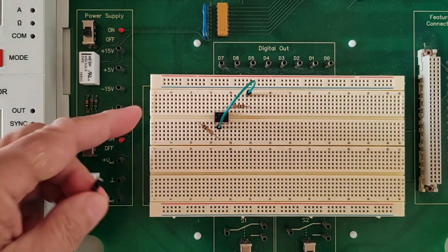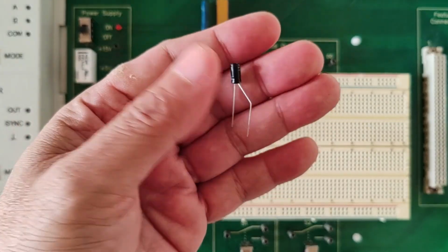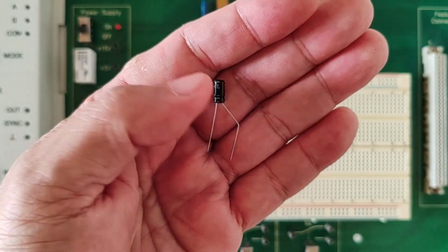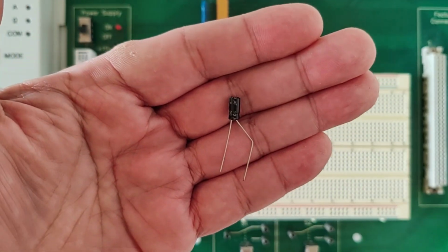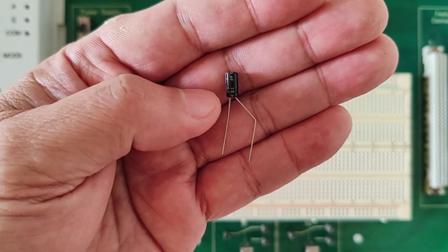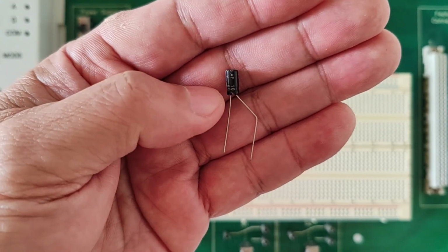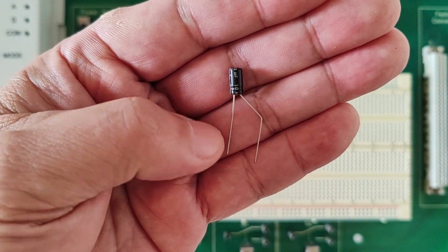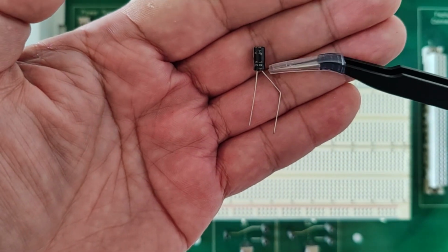And the other leg of that resistor, I'll connect it to a capacitor, this one, an electrolytic capacitor. If you remember on the schematic diagram in the video, the electrolytic capacitor carries a polarity, wherein the positive leg and the negative leg need to be identified. This is a 10 microfarad electrolytic capacitor, by the way. The negative terminal is the shorter leg. The longer leg is our positive.